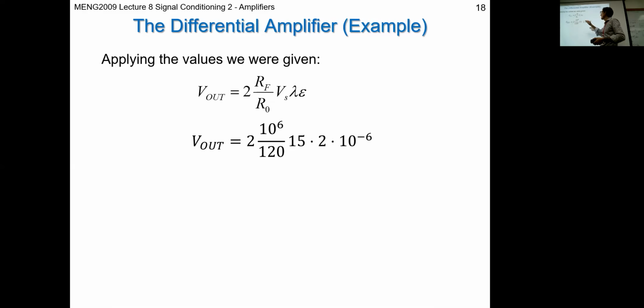setup. So that's a reasonable kind of output voltage that you can work with. It's not in the micro or millivolts ranges, which would be difficult. It's brought it up. So we've now applied our differential amp to a Wheatstone bridge, or in this case, a load cell setup, and got an output. Okay, so that's differential amp with an example.